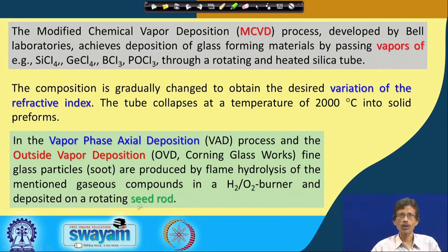These modifications can be achieved, for example, through vapor phase axial deposition. We consider one axis as the axial one and the base as the equatorial one, where the axis is perpendicular to the equatorial plane, but the deposition is achieved in the axial position, that is, when the glass fiber is coming out. In the axial position, deposition can be achieved through the vapor phase axial deposition or VAD technique.